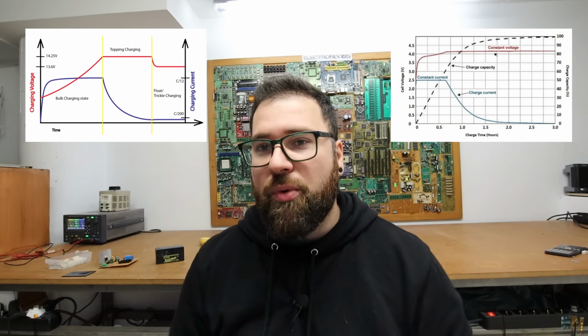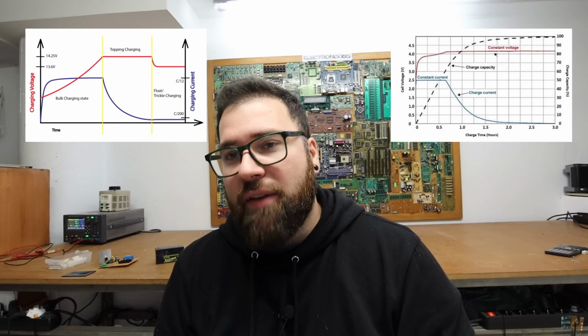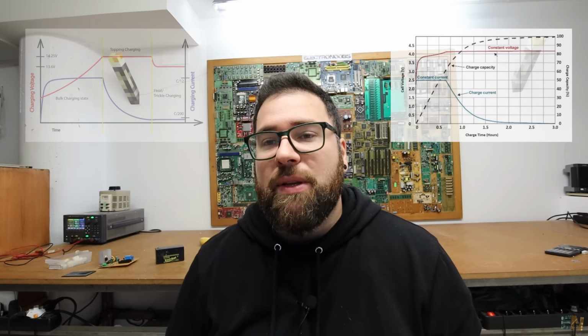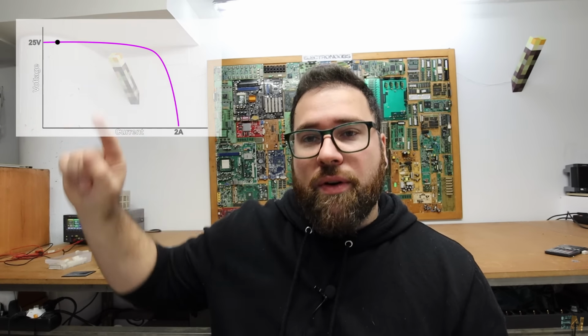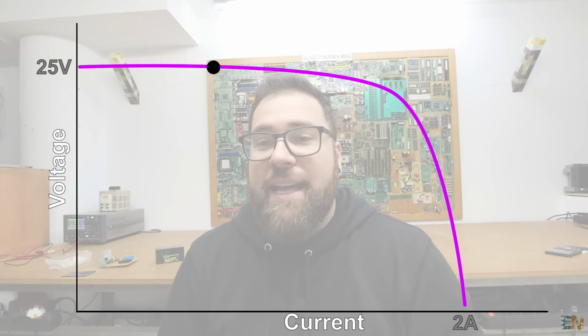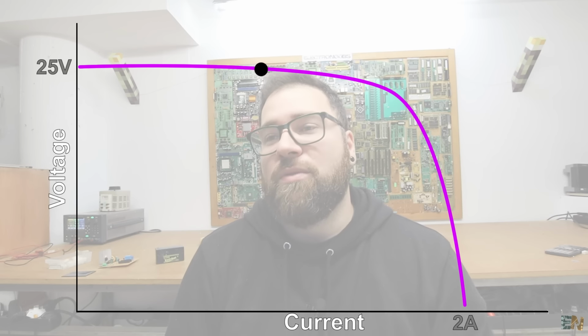Okay guys, so that's basically how an MPPT system works. I will post these graphs, which are very important, on my website as well. You have to understand that the MPPT will make a trial and error between current and voltage, and it will get a graph like this one where you change the current and the voltage value and you get the power. When you are on the peak, up on top of the power, you stay there and keep it steady, and in that way you get the maximum power.